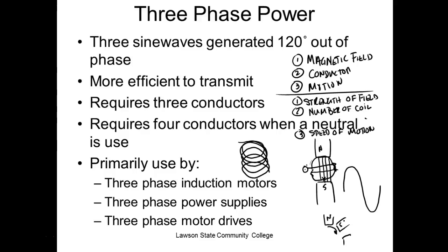And so every time it goes through there, and I don't know, this is a problem we have with cars. In cars, our alternator is constantly varying what? The speed of the motor. So if you're sitting there idling, your alternator's running at 1 speed. You step on the gas, your alternator runs up. Well, it wants to put out a higher voltage.